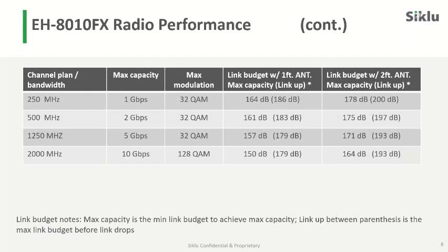So first, the transmit power control kicks in and tries to maintain the highest transmit power possible on the link, and if the rain density is even higher, then only later will the modulation go down to maintain signal quality on the far end, and it will start reducing the capacity on the link. So transmit power control first and modulation second.